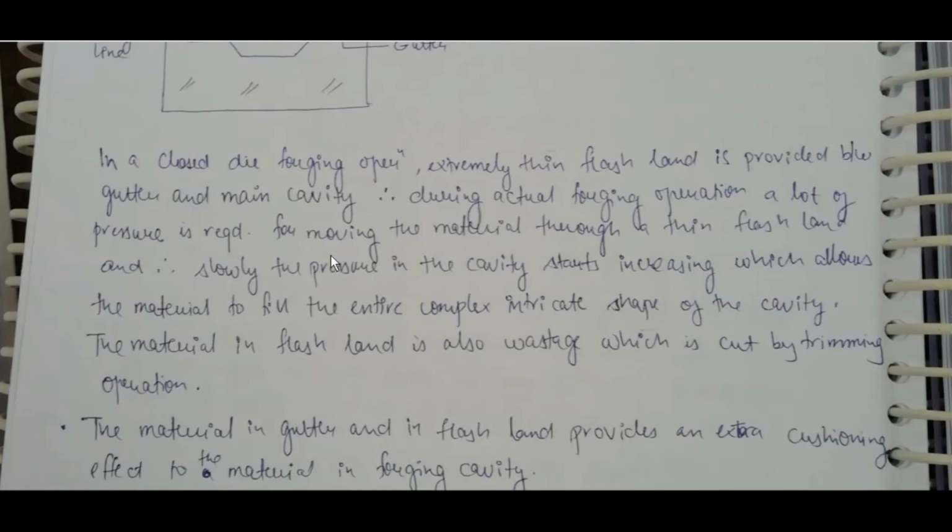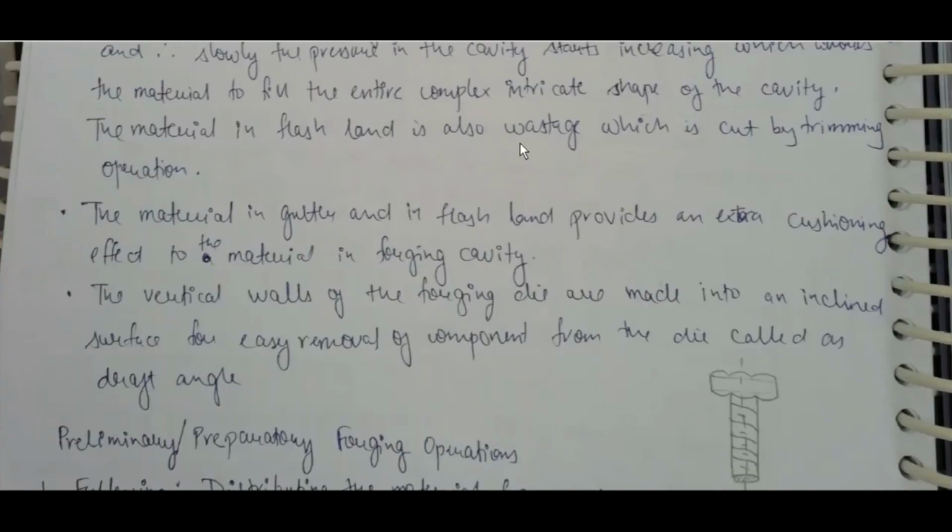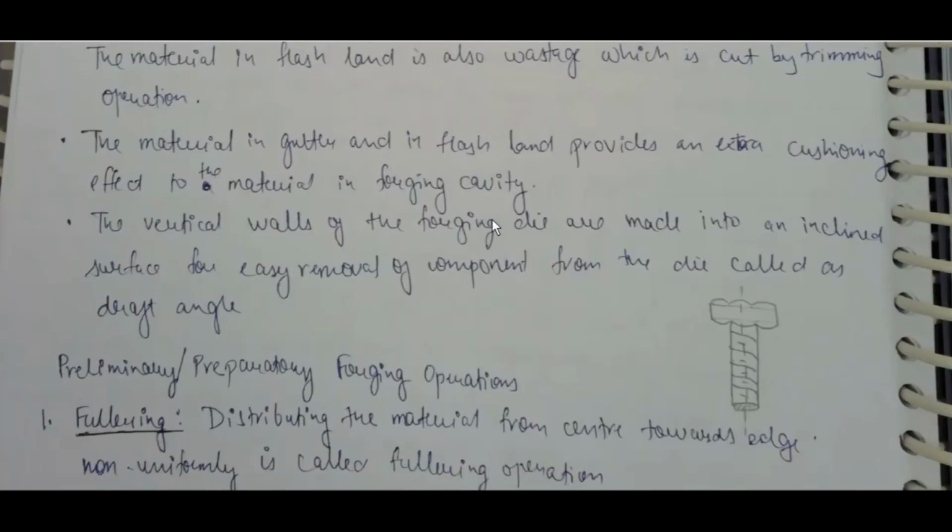The advantage of forging operation: improved physical properties. Grain orientation is possible. The forging method for reducing the diameter of a bar and making it longer is termed fullering. Enlist the sequence of operations required to produce a hexagonal head bolt: upsetting, edging, flattening, blocking, finishing, trimming.